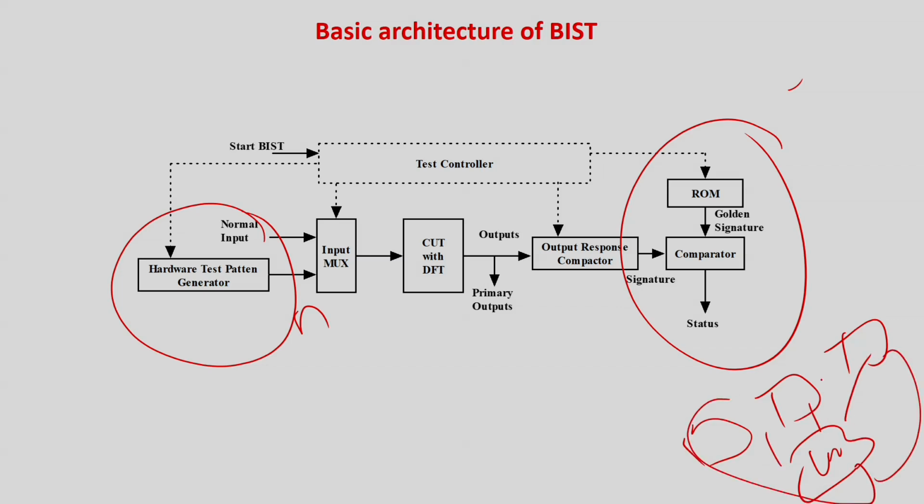This is a simple algorithm for a digital counter or a pattern generator. These are the D-flops maybe. The inputs to the D-flops come from a combinational circuit, and the outputs of the D-flops again go to the combinational circuit. So basically it's a counter. If the present state is 0 0 0 0, the next state will become 0 0 0 1.